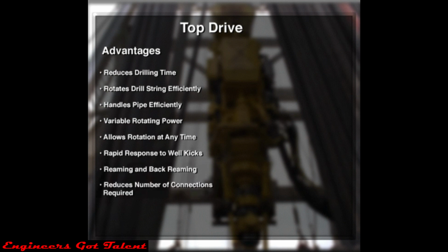If the crew can make up 3-joint stands of pipe before drilling starts, a top drive can drill triple stands instead of just 1 joint, as is necessary on a Kelly drive rig. Making up 3-joint stands reduces the number of connections required to 1/3. In many cases on large offshore rigs, the crew no longer needs to lay down pipe between wells. That is, the crew can set stands back vertically in the derrick, and the rig can be moved a short distance without the pipe being laid down.